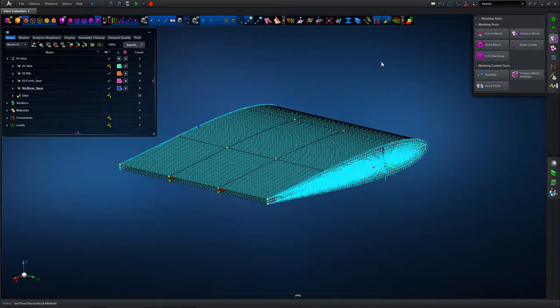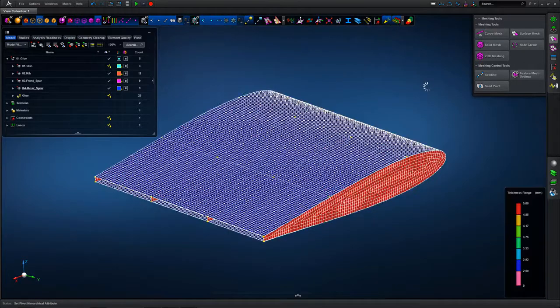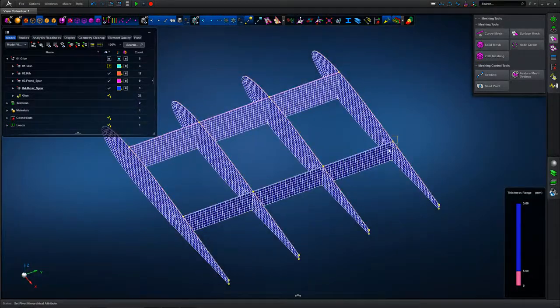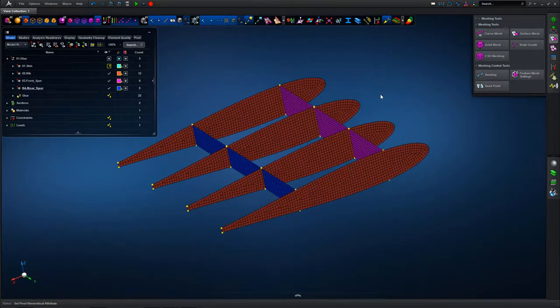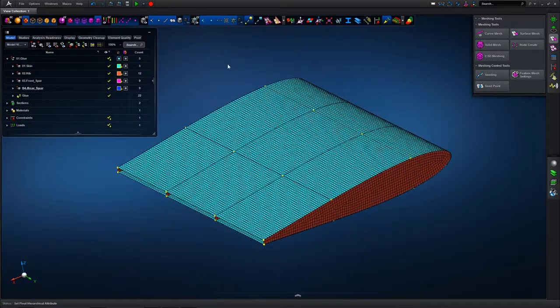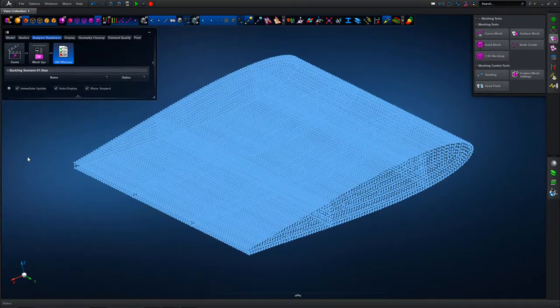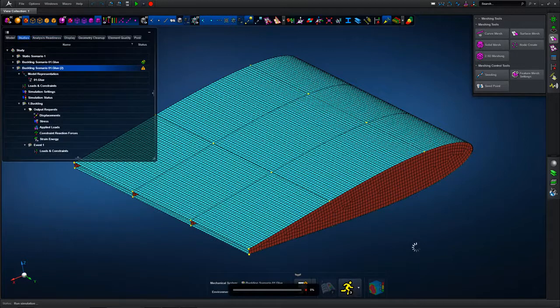Again, the generative nature of Apex means that a simple remeshing cycles all the way through the model, so we don't need to redefine properties, material definitions, loads and boundary conditions, or even the glued contact as highlighted in this case. And again, 3D shell thickness displayed, so showing the full model, and then going into analysis readiness again, or setting the job up, and we can rerun the buckling case. And again, very quick to rerun.